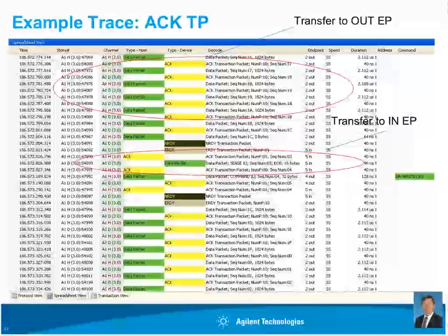It's also important to be able to use complex types of operation if you're looking for specific types of data. Here's a link of monitoring write commands using the USB attached SCSI protocol, which is the new mass storage specification. Well, there are actually 5 pipes that are set up in that communication, and you may only be concerned about one of them.